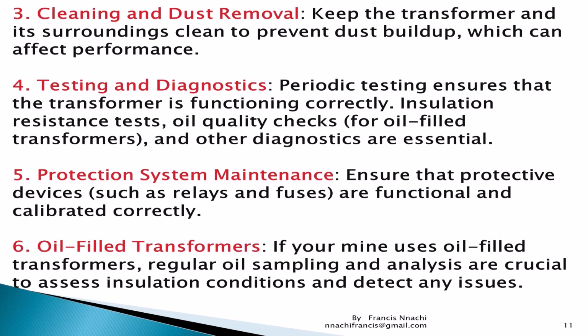Then oil filled transformers. So if your mine uses oil filled transformers, regular oil sampling and analysis are crucial to assess insulation conditions and detect any issue. Okay, did you get that? All right, so that's all about that.